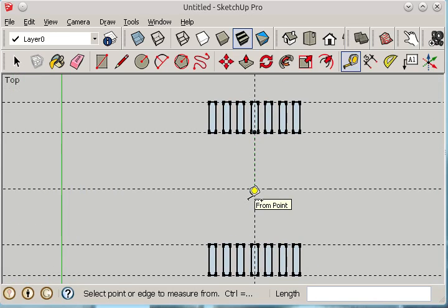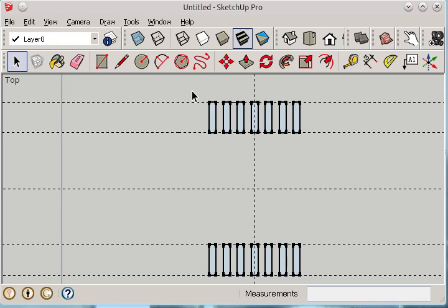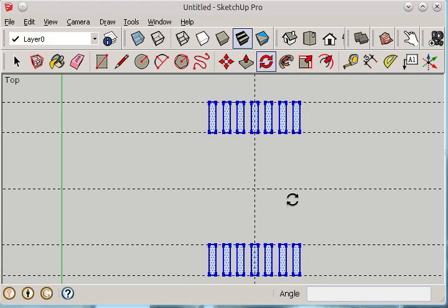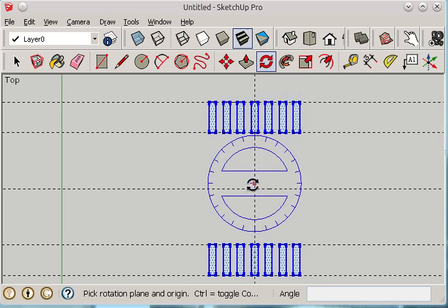For general footprint editing, a special symmetry function would be very great, so you can place any figure or any object in the center of the drawing or a predefined drawing area. So I select all the pads, and I press Q, this is for rotation.